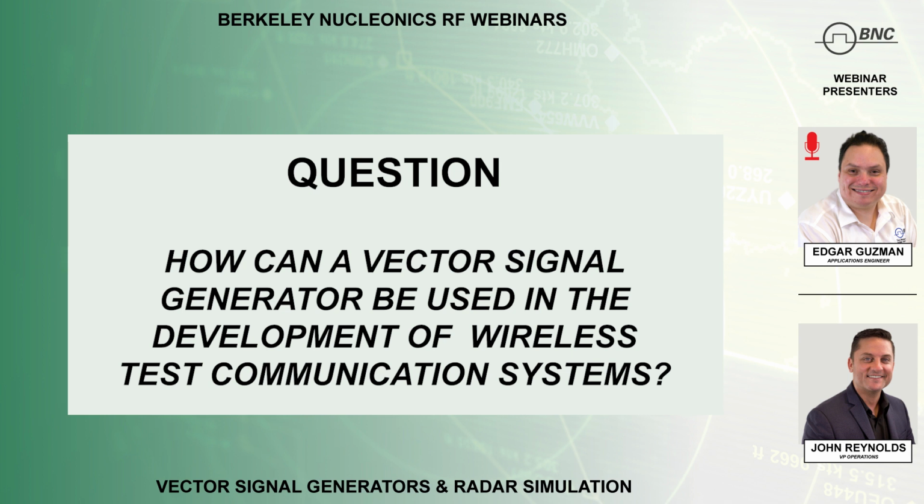If we could see it, we wouldn't even be able to see past my hand here, because we're just constantly surrounded by signals constantly. So you need to know how your system is going to react to that, especially in a house where there's walls, air conditioners, heaters, all those things putting out large EM fields and noise. So with a vector signal generator you're able to simulate and kind of prepare for that.